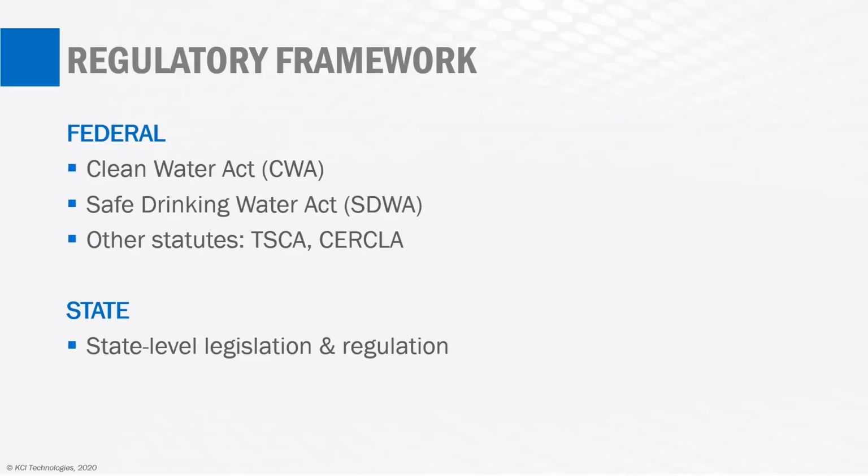And so the limitations under NPDES permits are generally driven by water quality considerations. So there might be human health considerations, there might be aquatic life considerations, and all those water quality criteria are set either by EPA or by the states, and then those become the criteria by which the discharge permits for the POTWs are set. And so there is a mechanism for EPA or the states to set a water quality criterion with respect to any one of these PFAS chemicals.